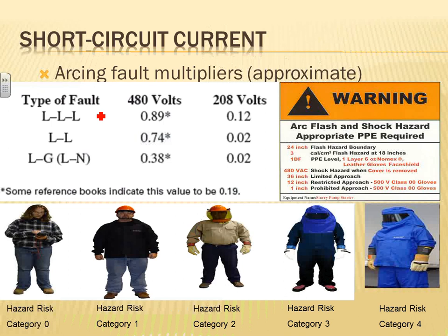As long as we're doing a short circuit, one of the advantages of having a short circuit calculation, guys, is the arc flash. When we do the short circuit calculation, if you're lucky, you have a bolted short circuit, meaning you take phase A, B, and C and bolt them together literally with a piece of copper, and you flip the switch. That will give you the highest amount of current, no arcing, no sparking, and the circuit breaker will immediately trip if it's sized appropriately. Now, if you're not lucky, you drop something inside your switchgear and you have a high impedance short or a ground fault.